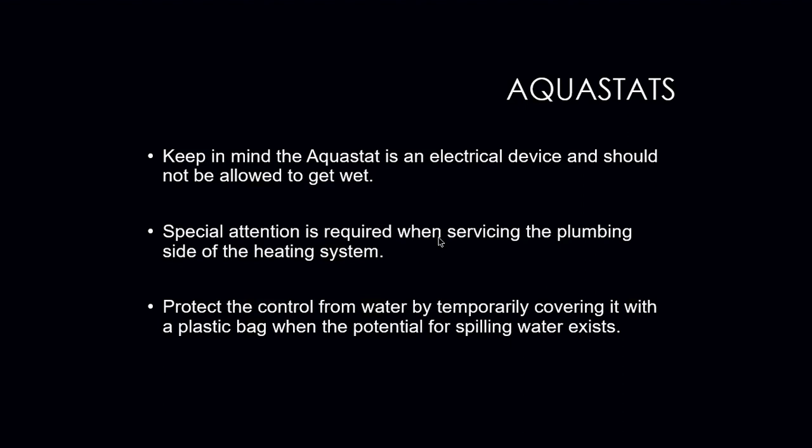It is always important to keep in mind that the Aquastat is an electrical device and should never get wet. Okay, you always have to pay close attention to that, especially when you're servicing it. Make sure that nothing is leaking on it. Make sure it doesn't have any sort of damage, anything like that. If it does, it should be replaced.